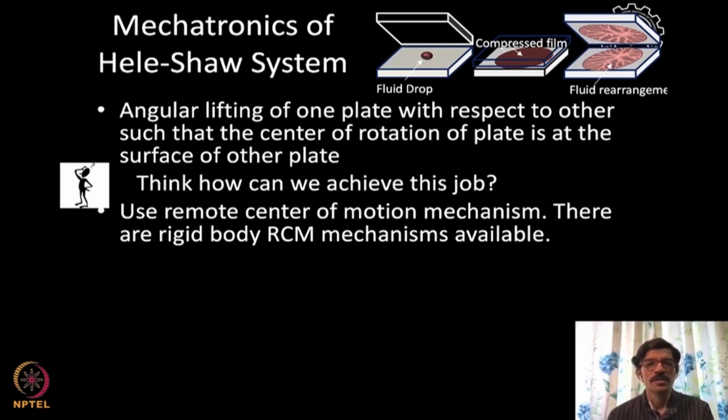We have seen the friction model: when you want to move something at very slow speed, it doesn't move, it just slips, and then again you stop, and when some force is exceeded, it slips again, like that. The stick-slip phenomenon will happen if you want to move at very slow speed. So that is the problem with friction.